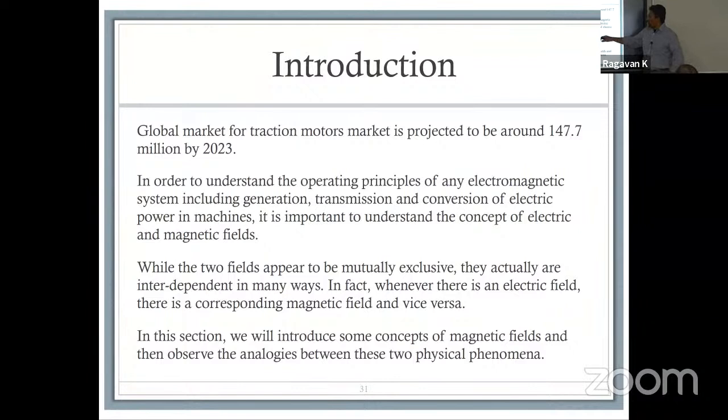So the two, oftentimes when you look at the magnetic fields, we think they are mutually exclusive. However, that's not the case. The fields that you see inside the electric machine really are very much integrated. And we're going to talk about magnetic fields, and essentially, what does it mean when we talk about electric and magnetic fields? Because once again, when you go into high voltage applications, as we talked about yesterday, we start looking at ideas like partial discharge, right? I mean, electric fields are not a problem until it's a problem.